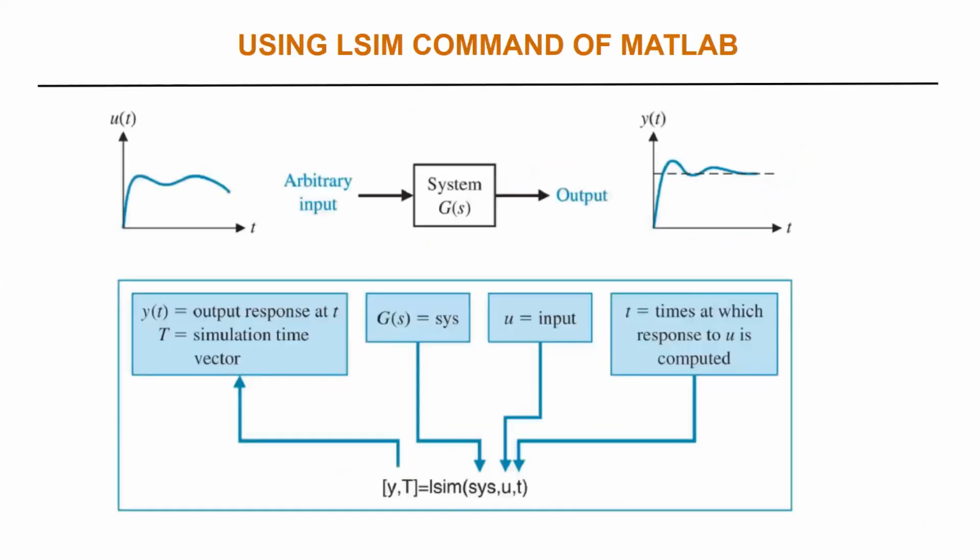If you want the MATLAB command, I can get the response by using MATLAB. This is one of the commands, lsim, and it is a good command to give you the response of the system. There is another command called step, and it will give you the step response and so on. Sometimes you'd like to get information from MATLAB.